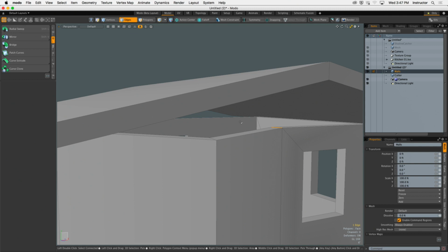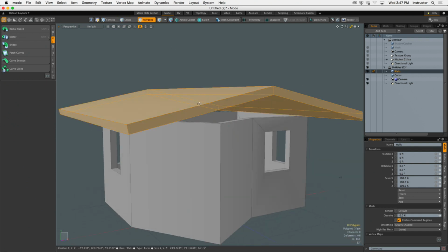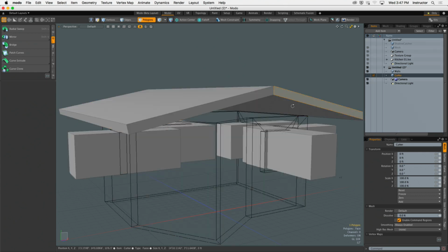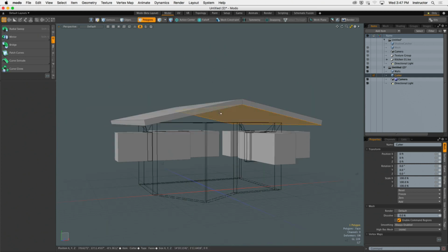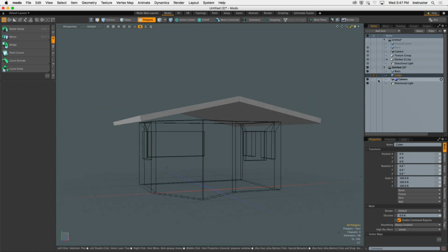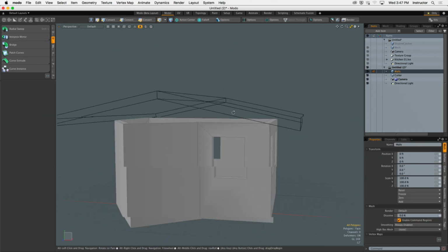Given what we've talked about today, what could be a strategy? Booleans. You got it. Let's do it. I'm going to take my roof and cut and paste it from the mesh item that it's currently on to this one. Now, I don't need my windows anymore, so I'm just going to delete them and return to my walls. There we go. So my roof's on a new layer.